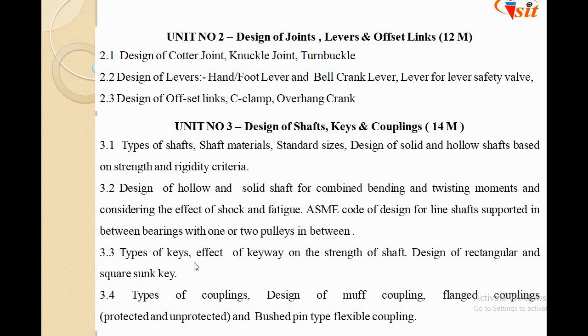The next part is the design of key. Under that we have to study the different types of keys, what is meant by a key, and what is the effect of keyway on the strength of the shaft. Now keyway is a rectangular slot which is provided on the shaft for inserting the key into it. When we have that slot, what will be the effect of that slot on the strength of the shaft, that we have to see here. From our subject point of view, we have restricted to the design of rectangular and square sunk key.